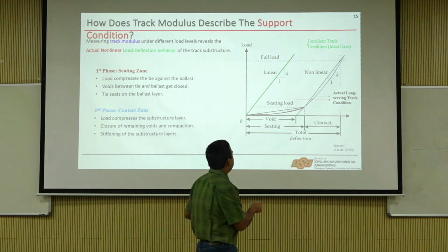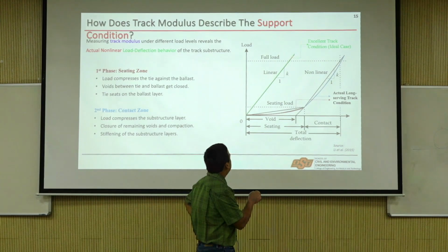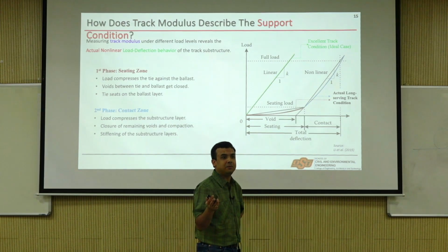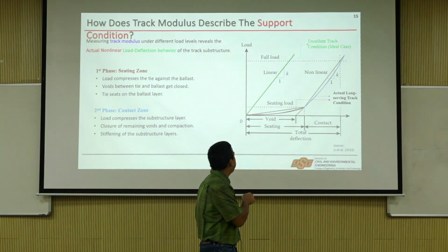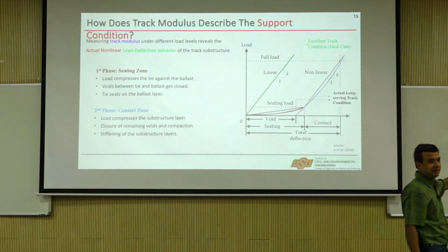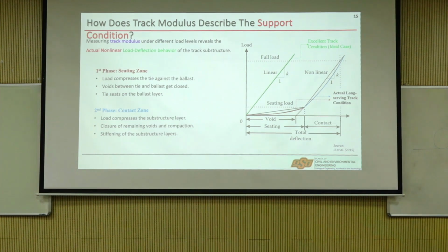And if somebody assumes a linear behavior and draws a line parallel to this k, it's almost like elastic modulus versus resilient modulus. Remember, elastic modulus happens at zero strain, but in the actual track with voids, the mobilized modulus or stiffness actually comes after some deformation, right? So this is how the mechanics works for tracks.